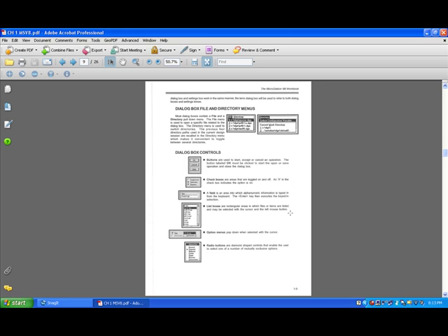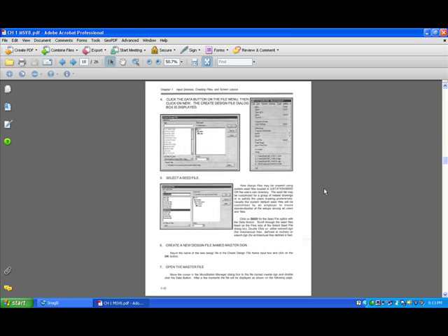The created design file just shows us here how we can open one up. You'll see a seed file at the bottom. This is kind of hard to see, but when you do start working with it, you'll see these seed files. You can select the one you want, or you can create your own. This can also be as simple as bringing up a previous drawing that you've done in the past and just doing a Save As and calling it something different to make a copy of that particular drawing. So it's not rocket science.